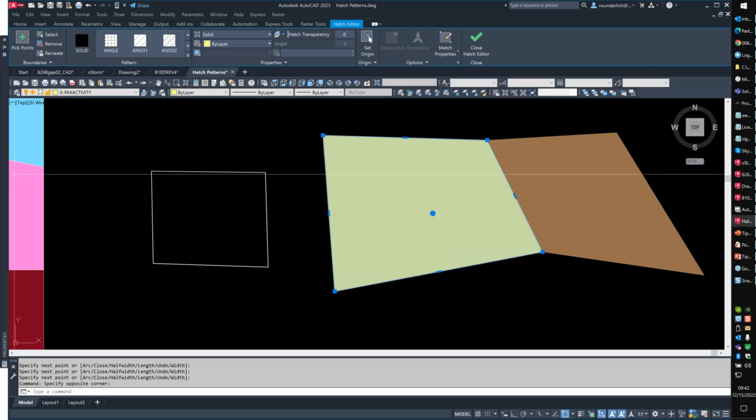All right, Leo, that's a good question. Yeah, line work shrink wrap usually weeds the polyline. I've had it not always be successful depending on how the polyline was built. That's why I put the caveat in there. It does work most of the time. I've had it not work before.